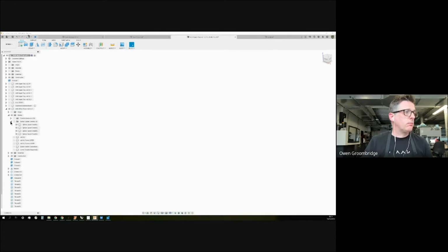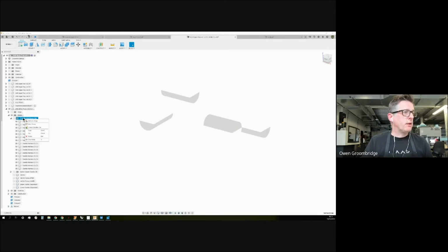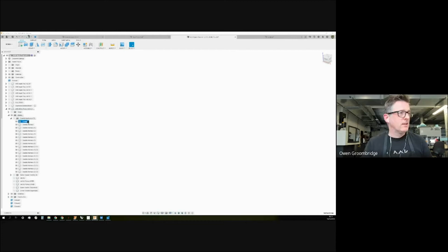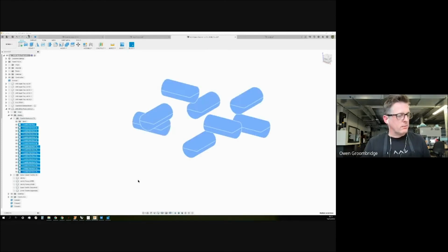So not that one. Let's have this one. Within Cradle interfaces, I'm going to go new group. This will be the demo group, so it's group 4, G4S, Demo. All right, so there's the demo. Which ones do I want to select? I'm going to select the top one, hold shift, select the bottom one, then hold control and individually deselect the ones I don't want, like those guys.